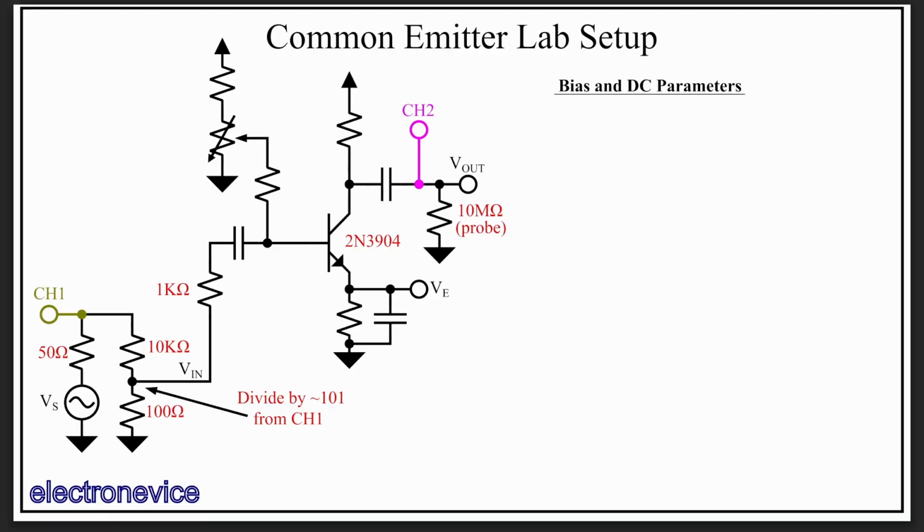Now let's think about what we want to do for the collector current. As with most amplifier circuits, the decision for each parameter is a fairly complicated optimization problem with many dimensions. To keep things simple, we will choose a fairly arbitrary collector current of 1 milliamp, which is not an unusual collector current. It's not too high, and the transistor has a decent typical beta of above 100 at 1 milliamp, according to the datasheet. It also keeps the transistor's transconductance relatively high, which keeps Rm low and allows us to use a smaller collector resistance while maintaining a high gain.